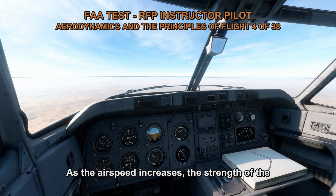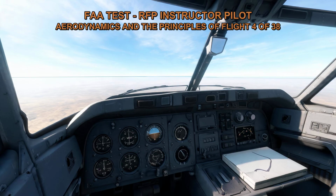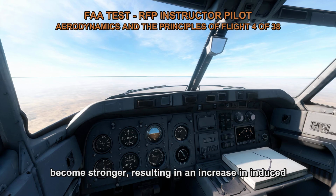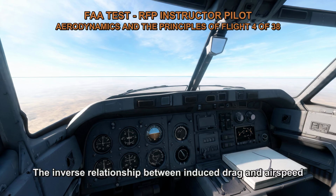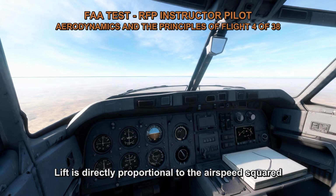As the airspeed increases, the strength of the wingtip vortices decreases, leading to a reduction in induced drag. Conversely, as the airspeed decreases, the wingtip vortices become stronger, resulting in an increase in induced drag. The inverse relationship between induced drag and airspeed can be explained by the lift equation. Lift is directly proportional to the airspeed squared.